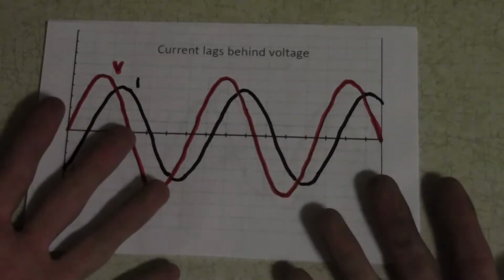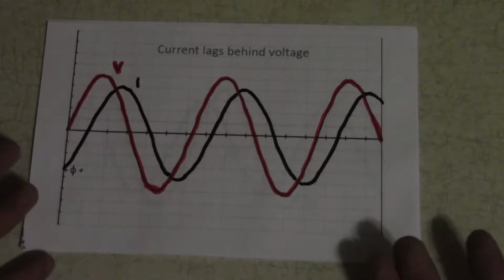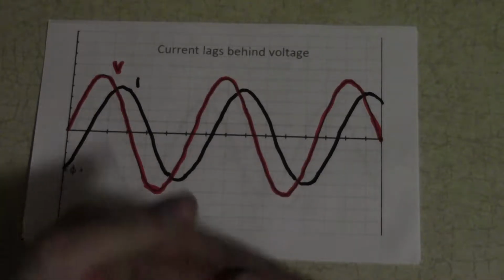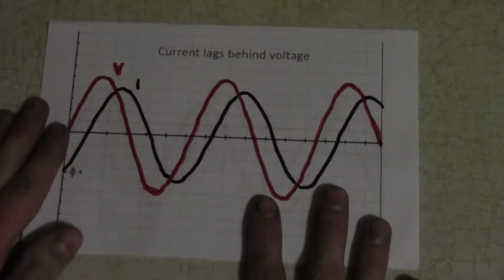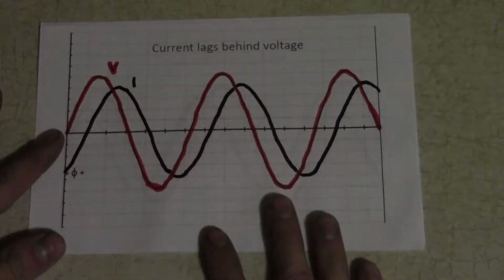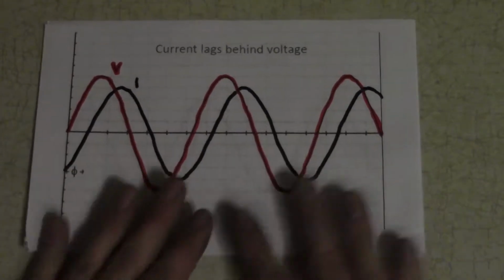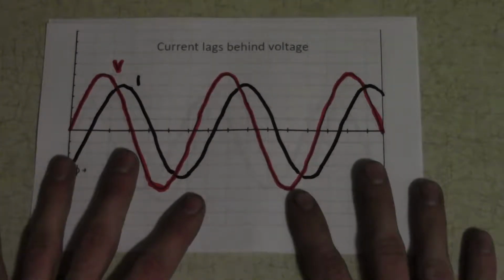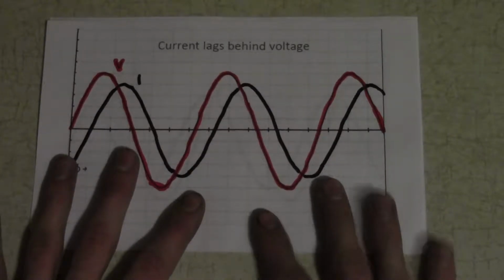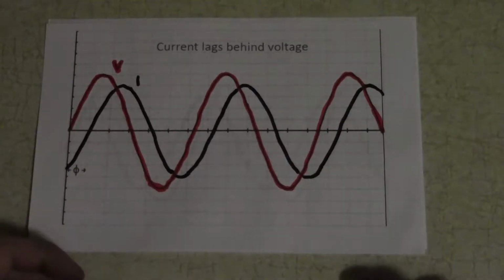Do I need to optimize my load? No, probably not. My generator probably puts out more current than I will ever need to worry about. However, just because I like more, I would like to have the ability to correct power factor. Should I ever be in a situation where I'm like, oh shoot, I'm running out of watts that my generator can deliver, I need to optimize this power factor so I can get the last little bit of wattage out of this generator and run as many things as possible, should I ever be in that situation.